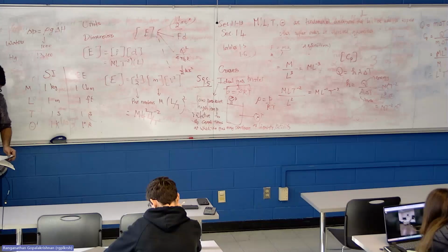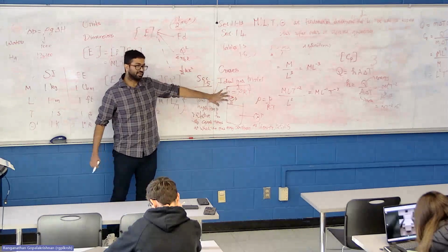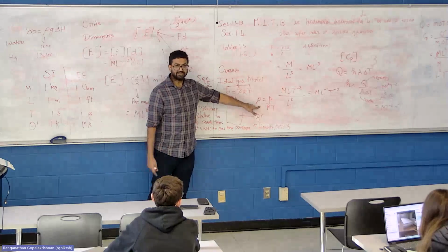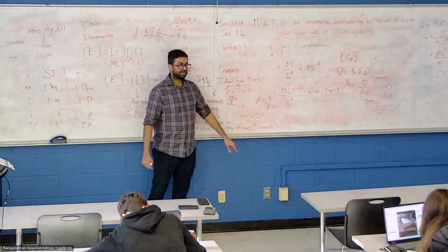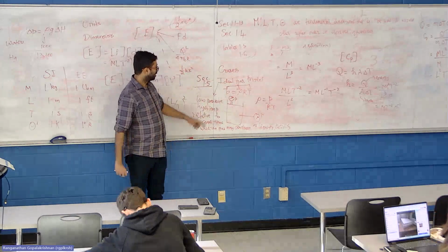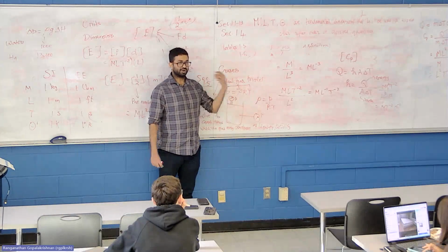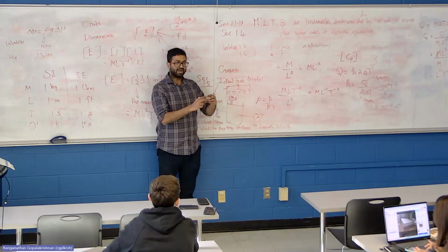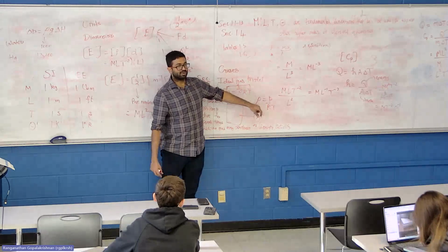So the main type of application of this ideal gas model, most often in this course, is to use it as a way to calculate density. Your specified pressure and temperature of the gas, and the density will be needed. So you plug in the values and get the density. The very careful engineer will add one more statement saying the pressure and temperature are such and such, and the condensation point of this material, which is methane or nitrogen or helium or carbon dioxide or whatever, is this. They will look up the condensation point of that and add a statement saying relative to that temperature, this is high enough, so I am using density equals P divided by R T.